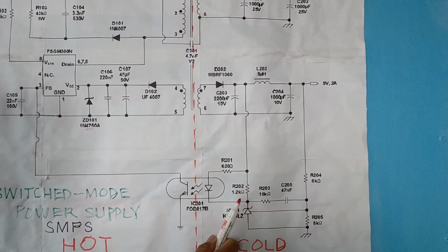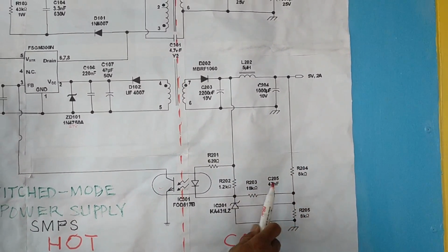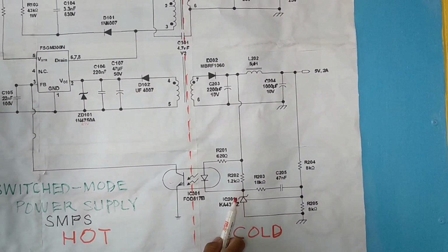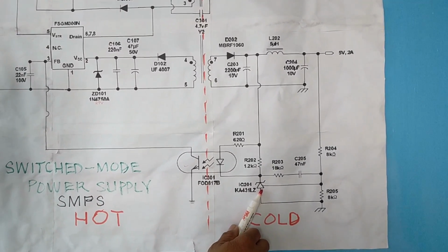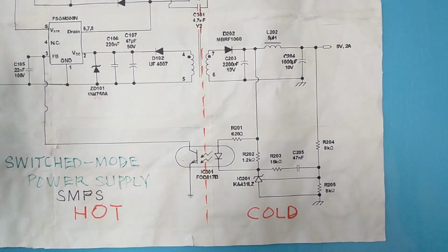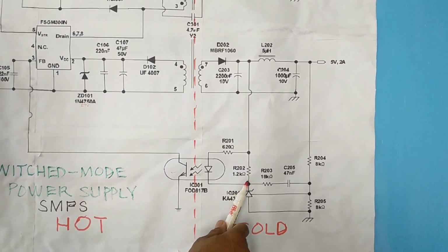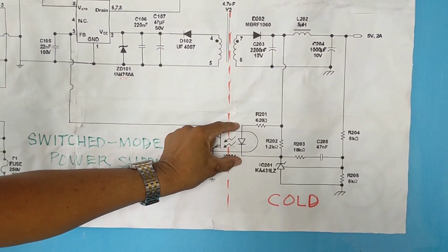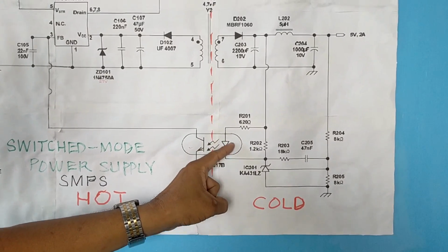The sensed change of voltage here, because there was a change of voltage being detected by this precision shunt regulator and compared to the reference 2.5 volts here. Then there's a difference. That error of 0.5 will be amplified before it is submitted to this optocoupler. This diode actually will drop 1 volt.